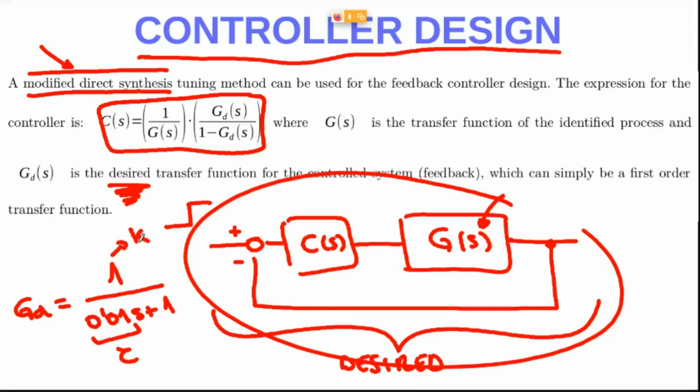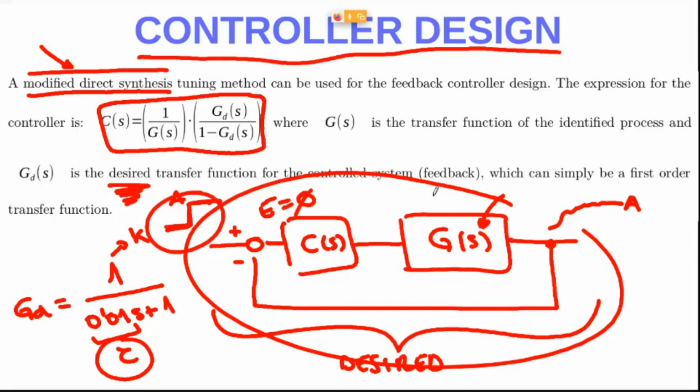For example, this is the time constant and this is the static gain. Why is the static gain equal to 1? Because this value in here, A, I hope that after this changes, this is A. So A minus A, the error will be equal to 0. That's the idea. And then this is the speed expected. This is a measure of how fast this controller reacts to the changes in the set point or to any disturbance that happens in here.